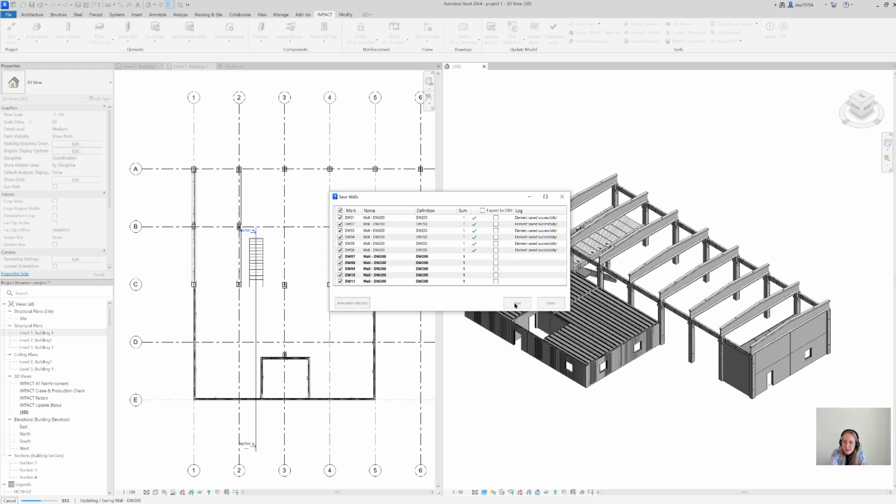And here's the smart part about Impact, because once reinforcement, lifts, and lattice girders are in the database, everything goes further to the shop drawing when we are doing that in Impact. We are now on the last double wall element, and we are soon ready to make a shop drawing.